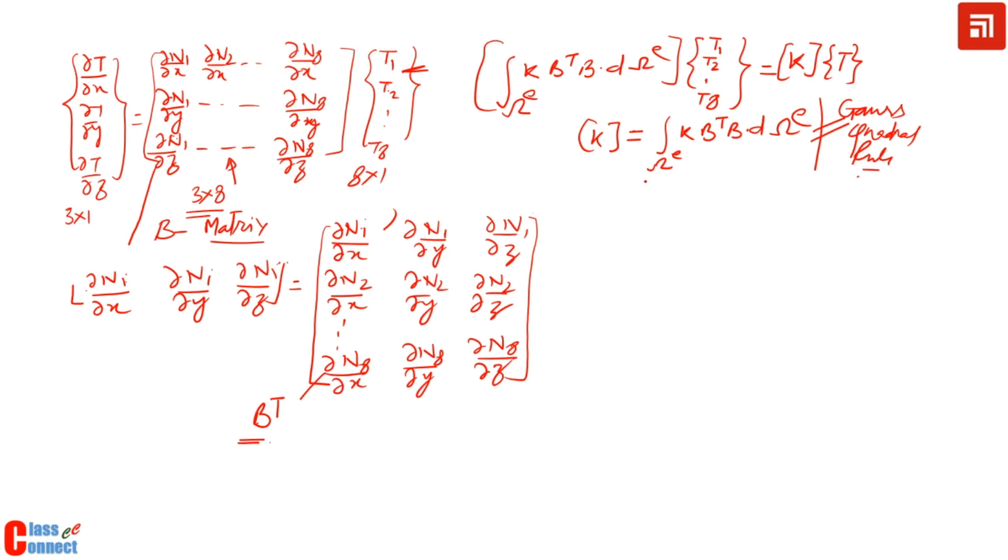So this is the first part of that equation, that K we have obtained. Now about the second part, if we remember, the second part was ∫ Ni h T dσ, that is on the boundary. So this can be written as Ni, where i is from 1 to 8, and this T is to be replaced with N times T.